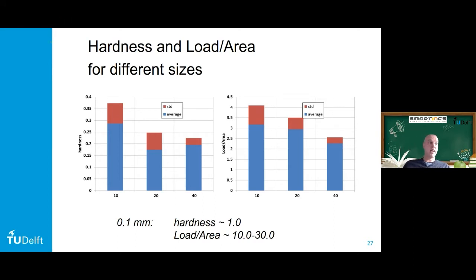So you see that there's a huge size effect even on this material level that should be taken into consideration, because if you also choose finite elements or other elements to do simulations, then you have to implement the strength of the material at that size of the element, because that's the element that will fracture. So you have to also determine the strength on that size. So you cannot just say, I use finite elements that I simulate things on a meter scale, and I just use the same model to scale it down to millimeter or micrometer and use the same properties. Because there is a size effect in the properties, so you have to implement the right properties at the right scale.